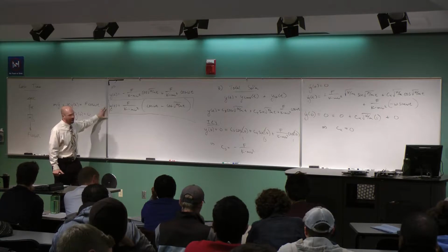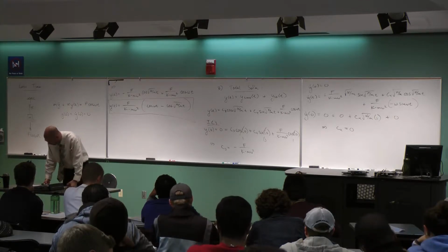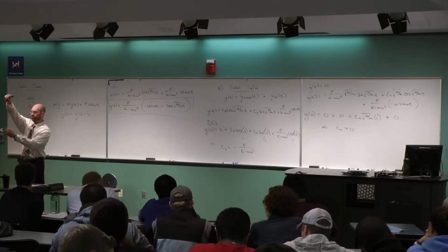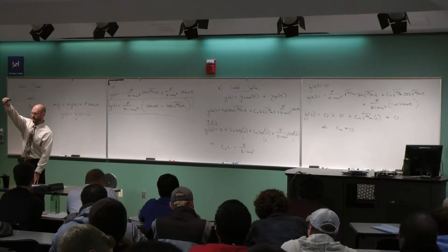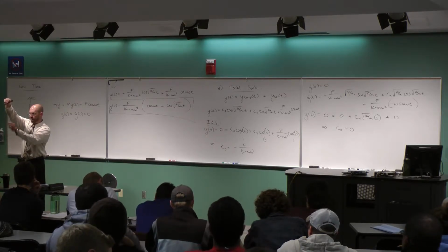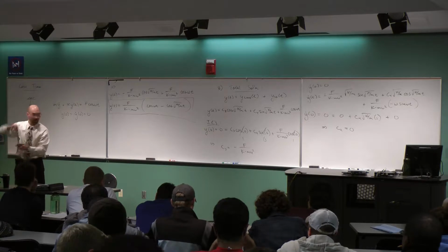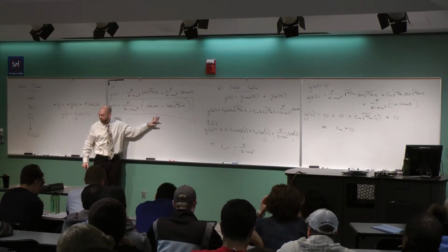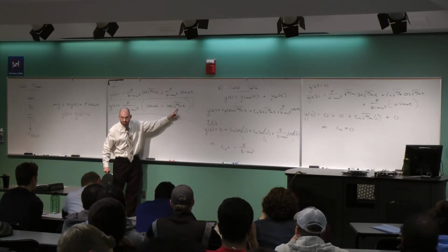Exact answers. All right, so the question is, what piece of physics can we get out of this? We solve all these problems because we want to understand some information. As I recapped at the beginning, if I just displace this and let it go, it oscillates at a frequency root k over m. That is the natural frequency. Then I can force it at some other frequency, faster or slower, and have an overall response of the system that looks like that. But this solution is only good if the forcing frequency omega is not exactly equal to this number.